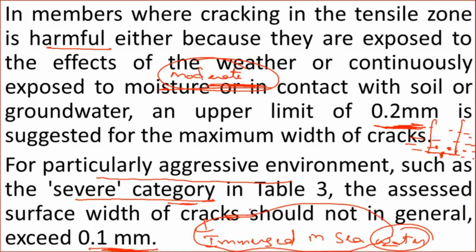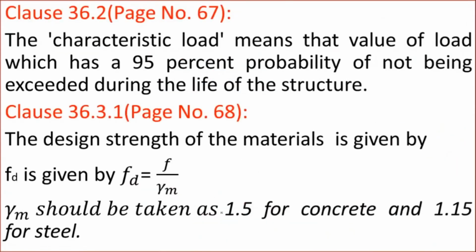So remember these three things again. In the mild condition, crack width should not exceed 0.3 mm. For the moderate condition, crack width should not exceed 0.2 mm. And in the severe condition, crack width should not exceed 0.1 mm.